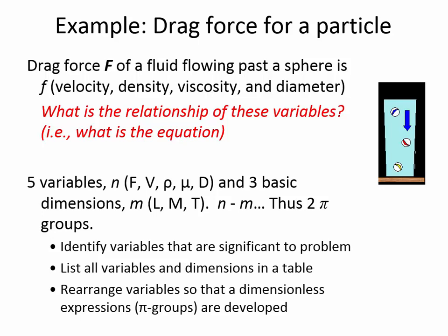Okay, so those are the units of the 1, 2, 3, 4, are we missing one? Density, thank you, yes, right. Density is units of kilograms per meter cubed, so that's mass divided by length cubed. So we're going to go through a process of combining all these together and trying to form dimensionless groups.